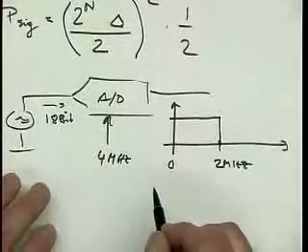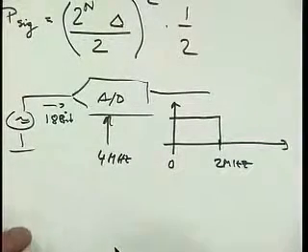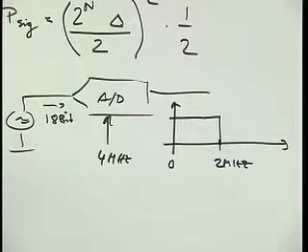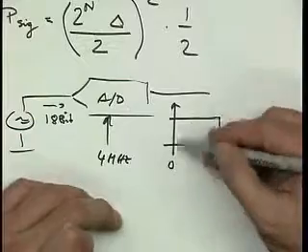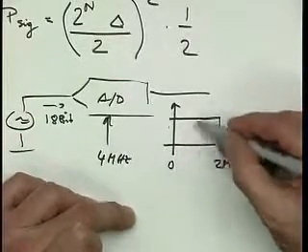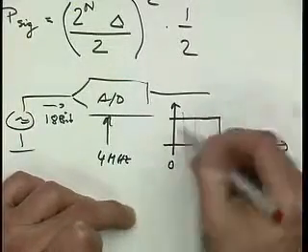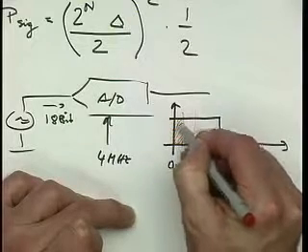Well, let's try to get an additional bit for this thing. If we want to get an additional bit, we have to cut the noise power by 4x, right? So we have to somehow slice this down by 4x. Well, we make 4 slices, and this is the only slice, for example, that we keep.